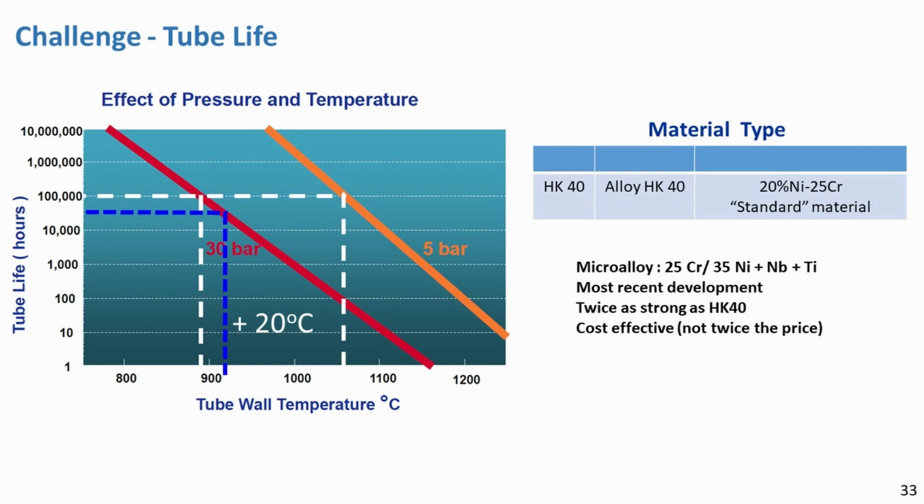One of the main challenges in the methane steam reformer is tube life. The reforming tubes are exposed to high temperatures and pressure. Tubes are expensive and account for a major part of the total cost. The reliability of the tubes is important, since tube failure can result in a long down period for retubing and hence loss of production. The mechanical tube design depends not only on the maximum metal temperature, but also on the maximum temperature gradient across the tube wall and the number of startups and shutdowns.